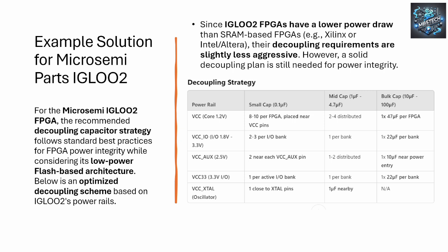You need to be familiar with the chipset you're using, and if not, then you need to use PI and SI simulation tools from Hyperlinks, ANSYS, CST, for example. That is the recommendation that I would give.